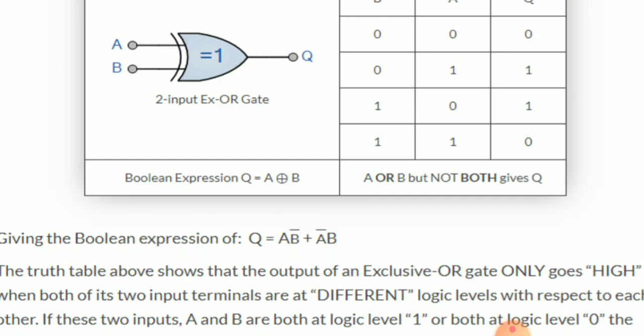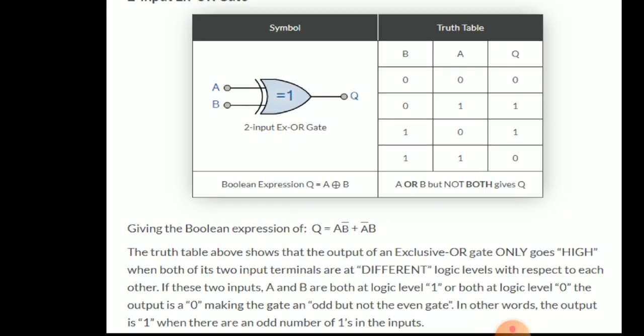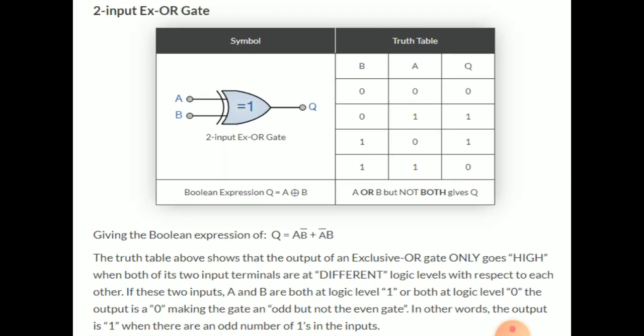As I said earlier, XOR can also be viewed as an addition modulo 2. XOR gates are used to implement binary addition in computers. That means it can be used in a half adder. The Boolean expression itself makes it clear that it can be used in half adders, subtractors, comparators and controlled inverters.